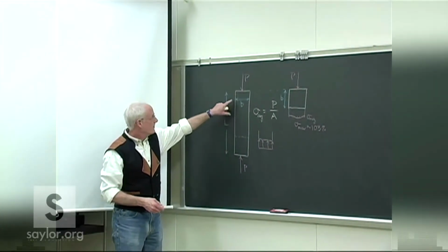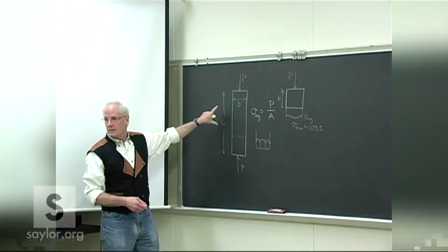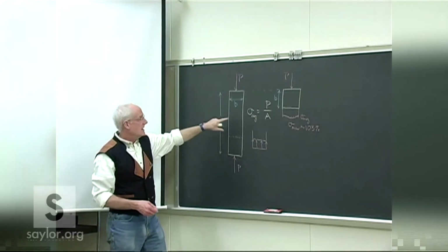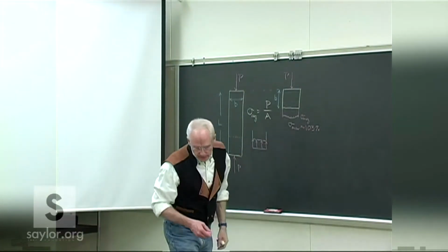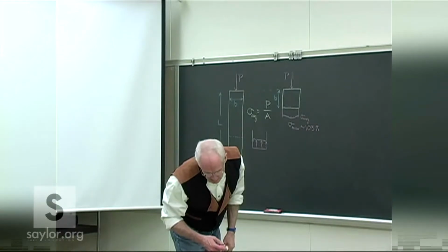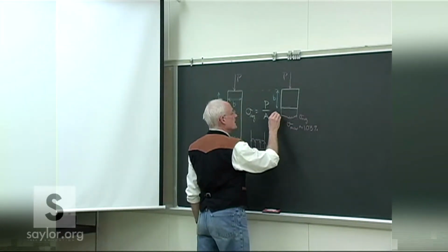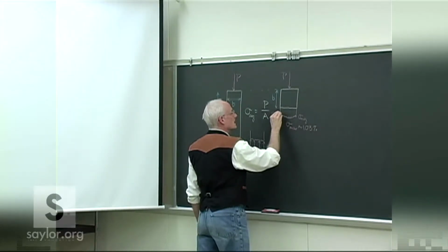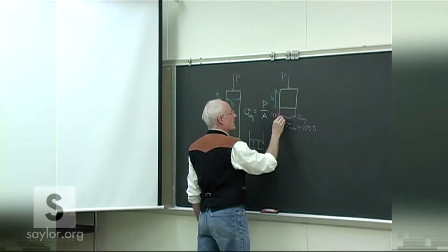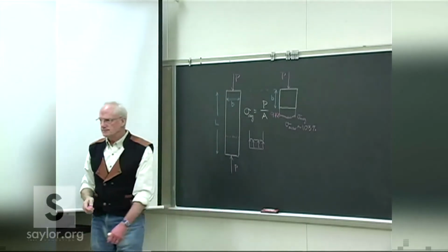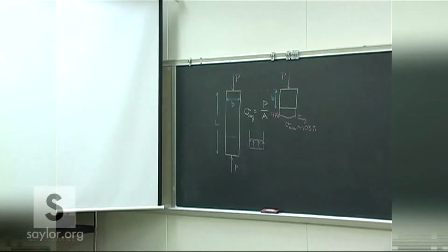The overwhelming majority of the length of the piece is at a negligibly different maximum stress than the minimum, than the average we use. The minimum stress is at about 97%. So we're not making that great of an error by using the average value for the stresses.